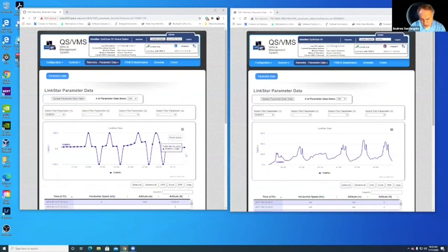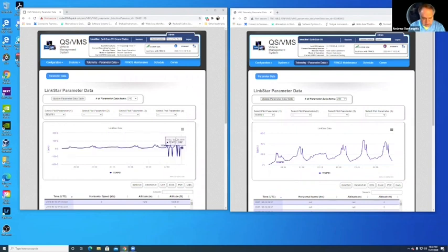So I might be inclined to put the satellite in safe hold mode because of what I'm looking at. I don't see the data which is pretty normal. I see that on the right, which is the satellite, what the actual satellite is seeing. But on the left, it is showing huge temperature swings, telling me the satellite might be in trouble. So my inclination would be to command the satellite to go into safe hold mode and turn off various sensors and instruments to bring this temperature down, which of course would affect the mission and its performance. Kind of a bad thing.